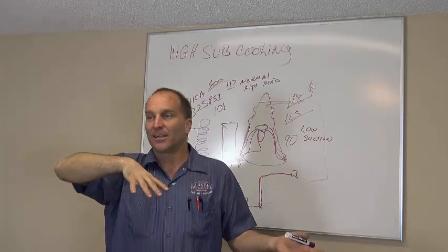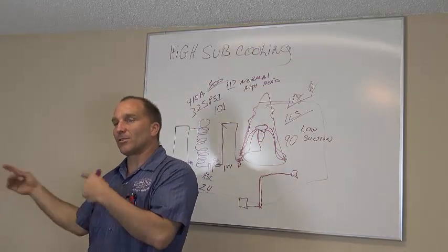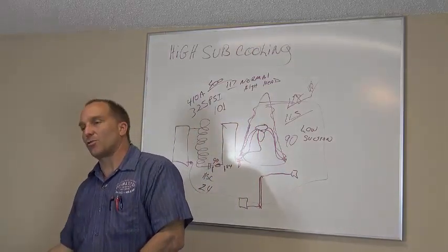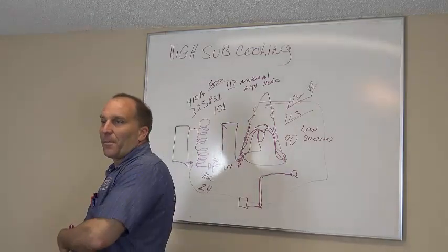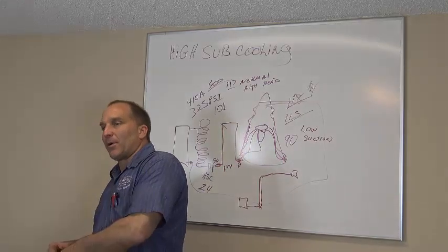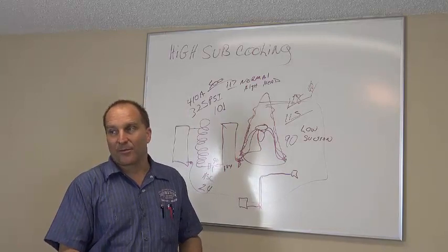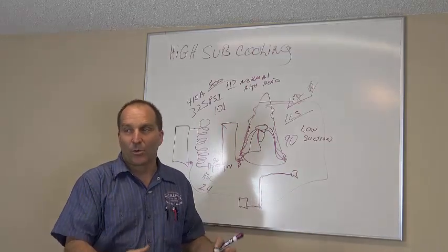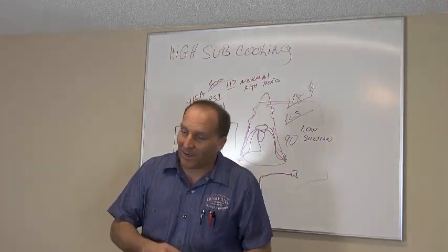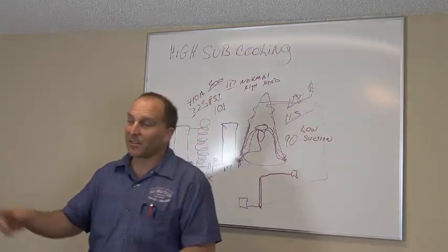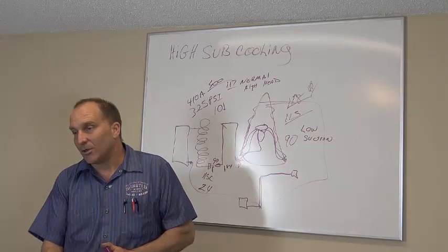Now you clean the condenser coils, you dropped your head pressure, you dropped your suction pressure, and now your coil starts to freeze because your pressures and temperatures drop down. He just got finished cleaning the condenser, now you've got to clean the evaporator coil. Then you clean the evaporator coil, and 2 days later his fan motor goes out because the bearings are bad. The condenser was so dirty it was causing the bearings to go bad, so you replaced the fan motor, and then 2 more days later his compressor fails because the system's been sucking in liquid all this time. Okay? So he's mad at you now.